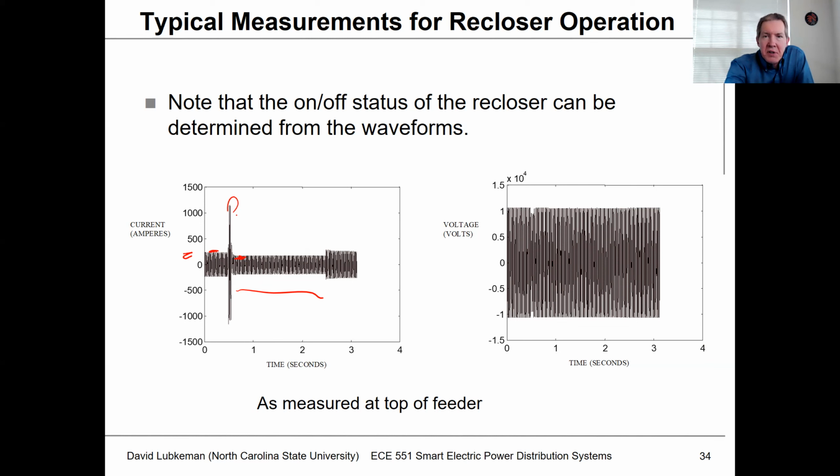That's not too good, obviously, for a customer below that recloser. But a customer on the adjacent, non-faulted circuit is only going to see this little glitch in the voltage during this operation. Now, this shows the reclosing occurring, and the load gets picked up again. The fault's gone. But if the fault were there again, it would jump up to a high value and you'd go through this whole cycle again. That sequence, where you have the fault and you open, is sometimes referred to as a shot. And reclosers could be set up for maybe 1, 2, or 3 shots where they'll try to clear the fault.